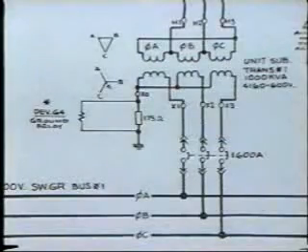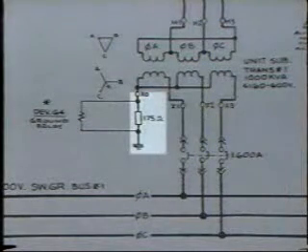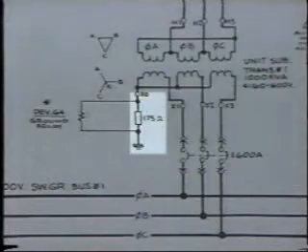We'll be discussing specific examples of impedance grounding in future tapes, but one point is very clear. When working on the power system, you must be alert for these various methods of grounding. Always check the schematic diagrams. The value of grounding resistance or impedance is usually indicated.